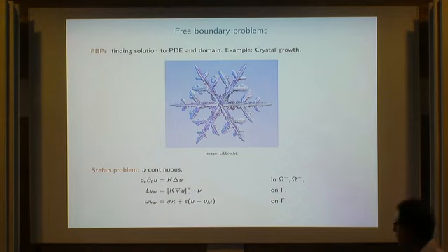Here I have the surface tension coefficient sigma, and kappa is the curvature. It's the isotropic case here, but you have a capillary term that regularizes the interface a bit, and that also gives rise to the typical crystalline structures as we see them in many applications. In the case of such crystals, we would have a kind of weighted mean curvature, a slightly different term.